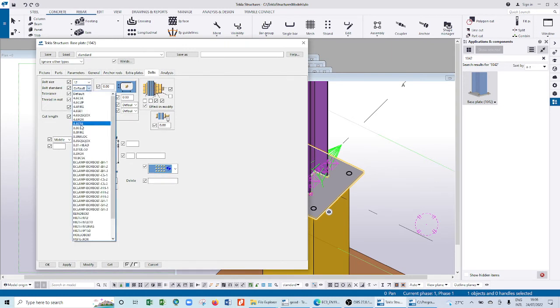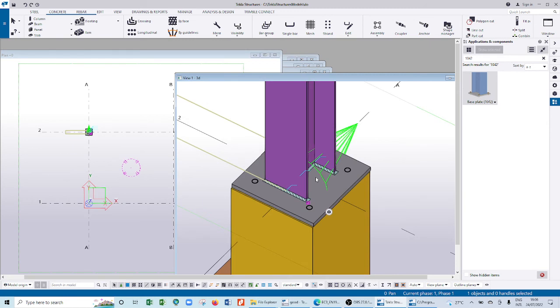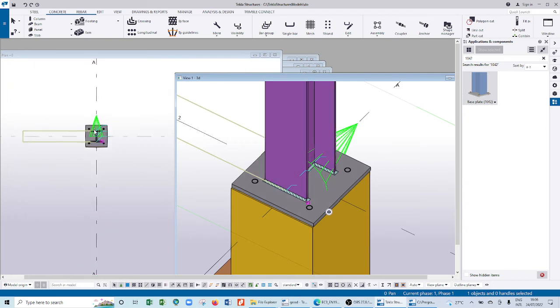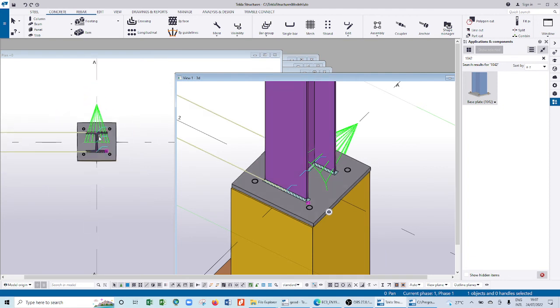Then the bolt type, you see here, we had selected and our design was 8.8. So I'm going to use 8.8 here. Commonly, you can find it in Uganda. After that, I press modify, apply, OK. See now my base plate just fits exactly. After you've done that, as you're working here, this is changing, meaning all those other parts will be changing.